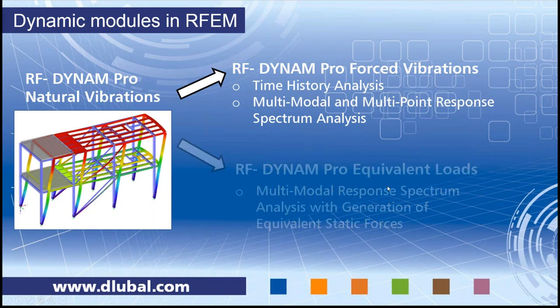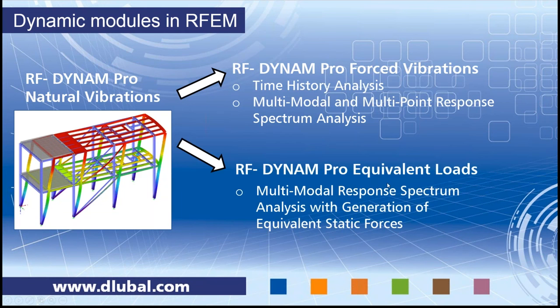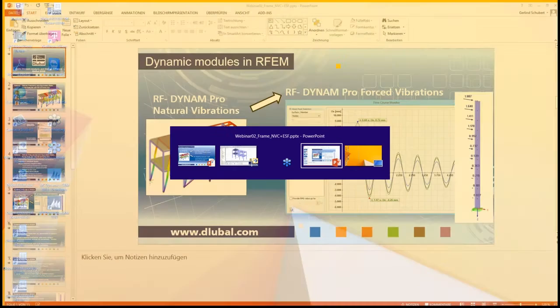The second module, and this is what we use today, is RF-DYNAM Pro Equivalent Loads. This is based on a multimodal response spectrum analysis, and this module explicitly generates equivalent static forces, so you get load cases and result combinations exported from this module. So, and now it's time to switch to the RFEM.